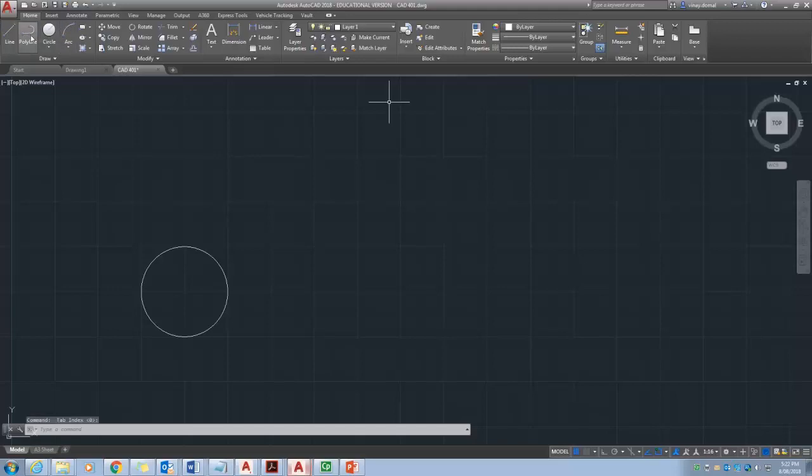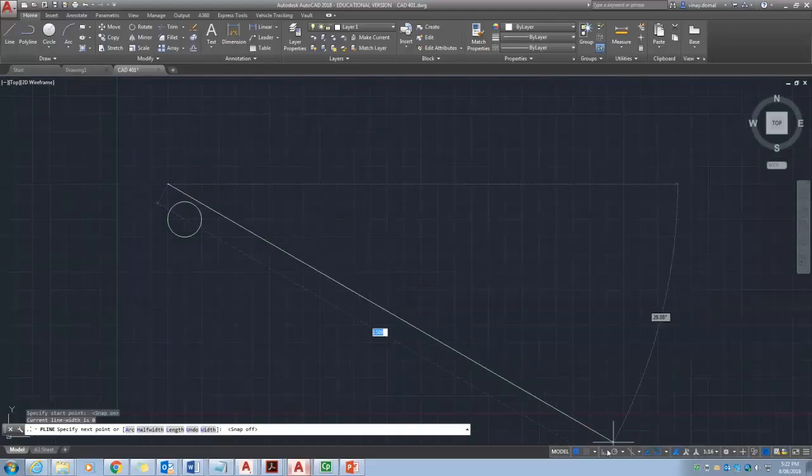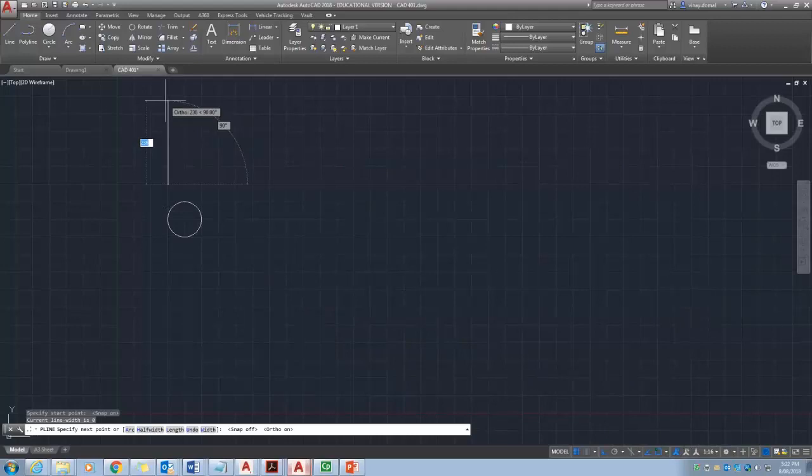Now select the polyline, because I want to draw it as one line. Select the quadrant, snap to the grid intersection. If you want the grid intersection, activate it again, so you've got your grid intersection there, and you can deactivate it. To go vertical like this, activate the ortho option, so you go 200 this way.